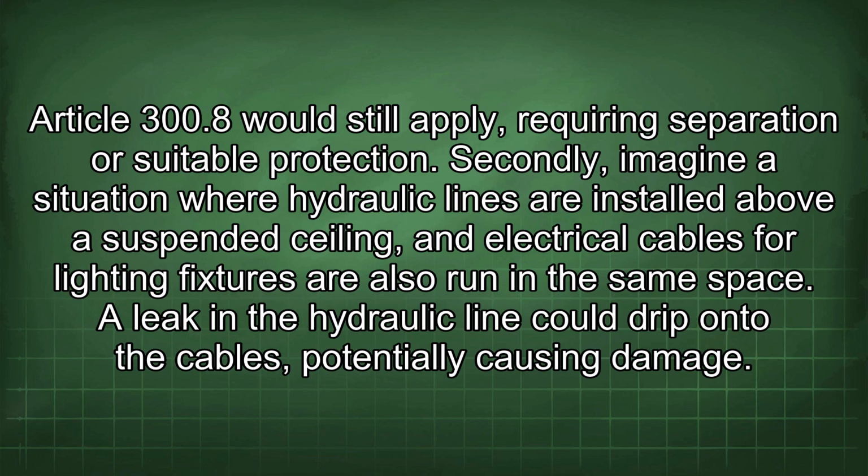Secondly, imagine a situation where hydraulic lines are installed above a suspended ceiling and electrical cables for lighting fixtures are also run in the same space. A leak in the hydraulic line could drip onto the cables, potentially causing damage.